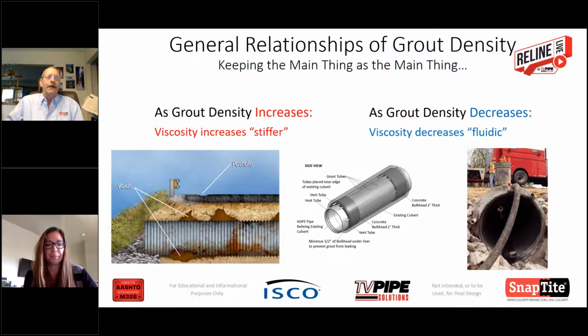And that's a key part to maintaining the road surface, because it's one thing to put a liner or a Band-Aid inside your host culvert, but if you don't do anything to address the materials that have been removed from around the host, you really haven't solved the problem of the road, and it's going to continue to settle and fail. So that's a great question. Okay.